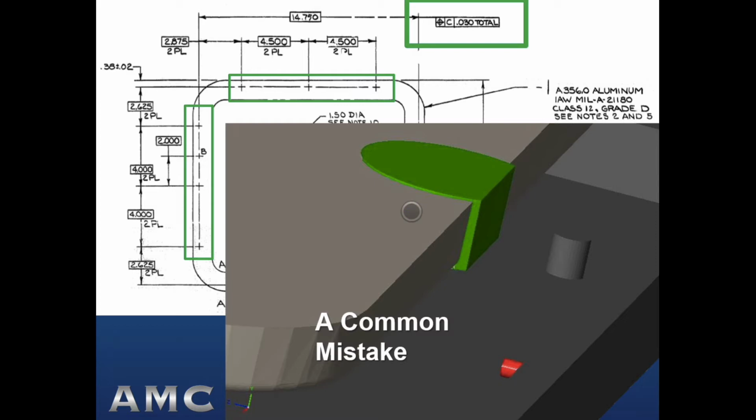But it's going to be wavy, and it's going to have some high spots and low spots, might even be slightly below the as-cast profile that's neighboring that grinding operation. It's media blasted to make the ground surface look as close as possible to the as-cast profile that is neighboring this area where it is ground.